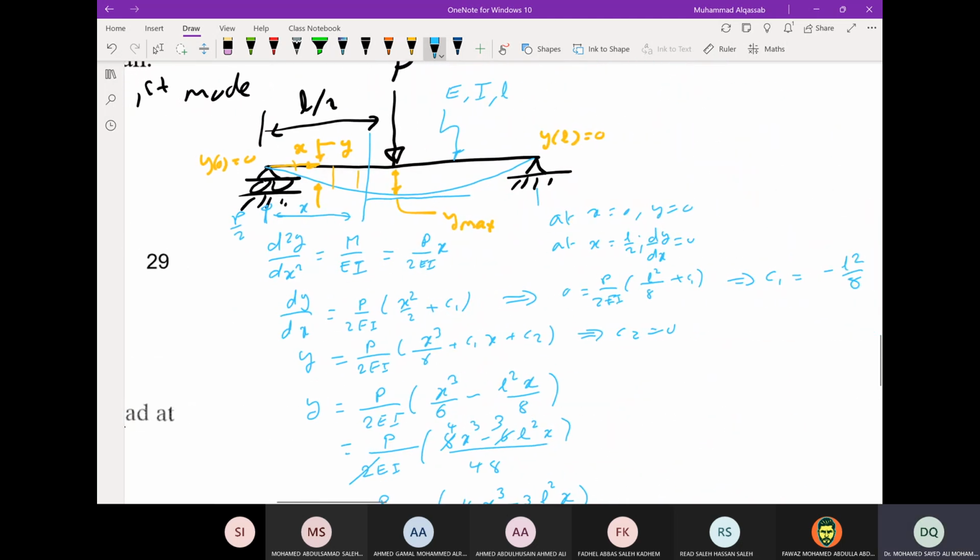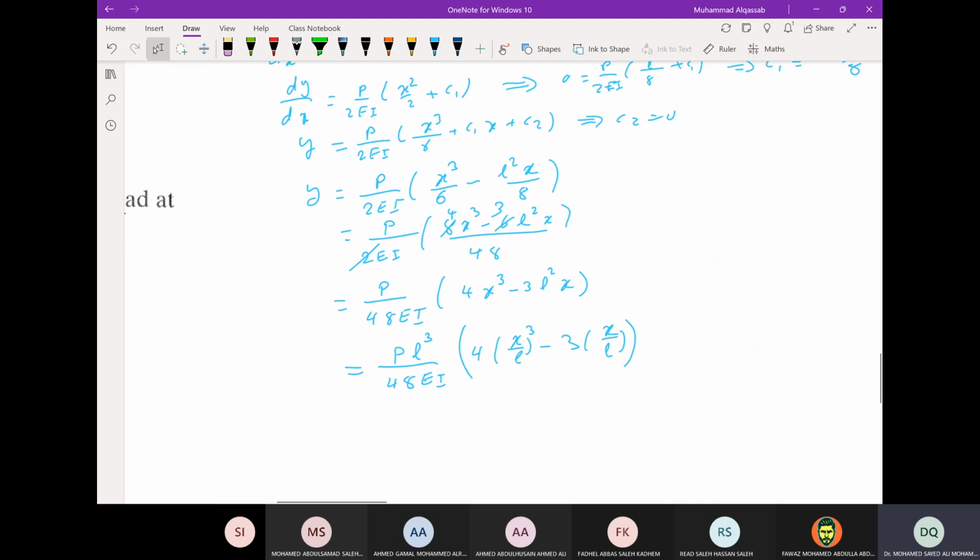Okay, but what we need is, of course, not this. This is the equation for deflection under concentrated load. But what we need from this equation, we will assume that the deflection shape will take this shape. You know, the deflection of the beam will take this shape under first mode. This is the assumption, which determines the shape as a function of x.